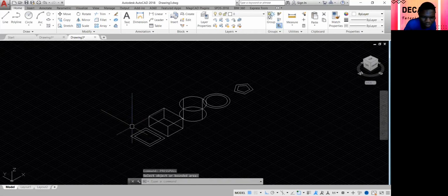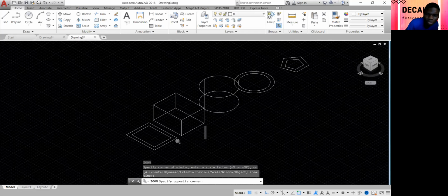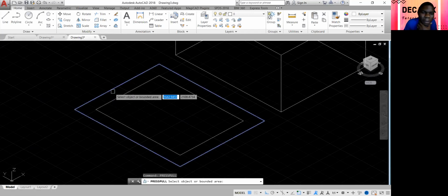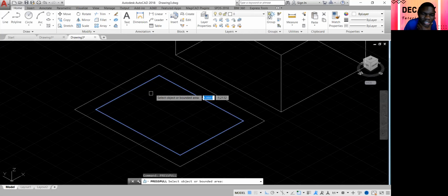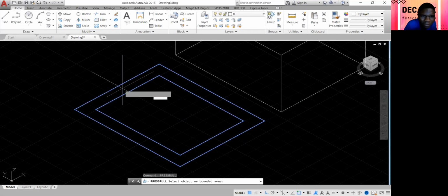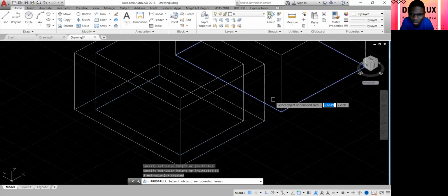So when you want to use press pull, let me use the zoom so you can see what I'm trying to do. When you want to use the press pull, mind you, press pull works for hollow objects whereby you don't need to pull this space. You want to pull this in between the hollow. You can see all the hollow part is now blue. Here is white, but once you bring your mouse, click and drag your hand up by 50 because it's hollow.